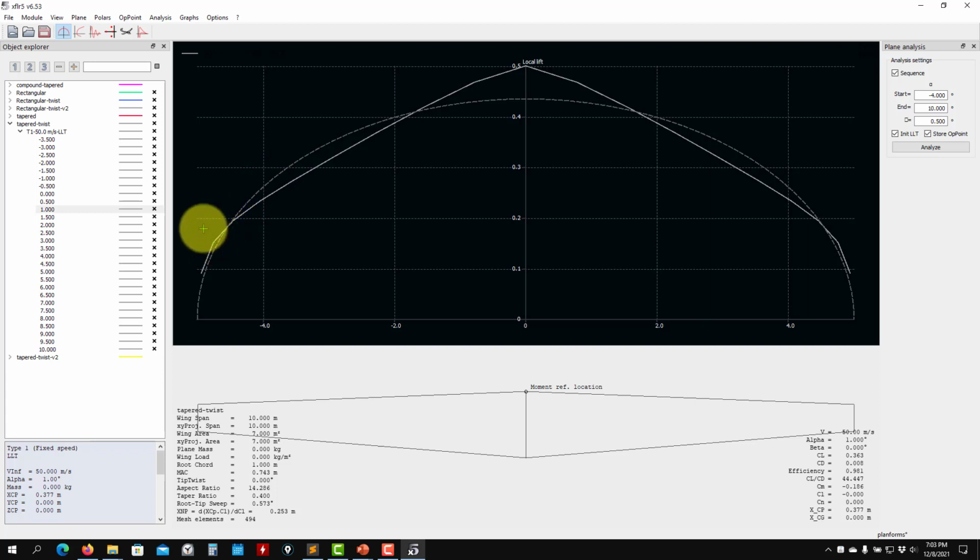The other solution is changing the wing chord. So you can change the wing chord, so you increase here a little bit, and decrease a little bit. But you see, when you start to do those modifications, you will be approximating an elliptical wing. So let's stay away from that one. So if you want to add sections, like for instance, a section 3 and 1, it's just to control the twist angle. And the idea is just to get it as close as possible in the outward part of your span.